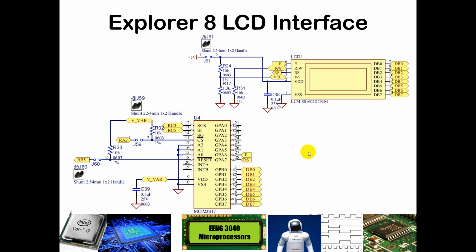And this external chip is basically an I/O expander. If you had a limited number of pins and you wanted to connect to a lot of external devices, you can use simply 4 pins to be able to control 10 different pins of output. So this allows us to conserve by using this.